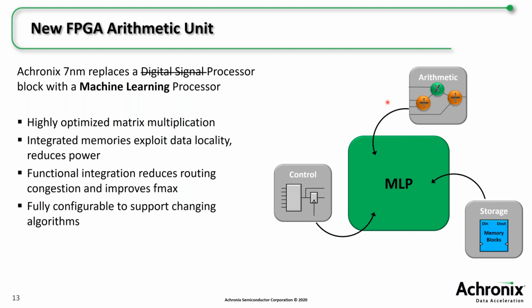You don't get something for nothing, and so the architecture is somewhat less efficient for FIR filters, particularly something like the architecture for a symmetric filter. You could still support it, but you would need some soft logic outside. But when you are applying it to matrix multiplication, you have much, much better performance, which outweighs any disadvantages in the other area.